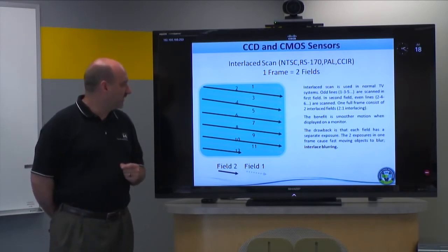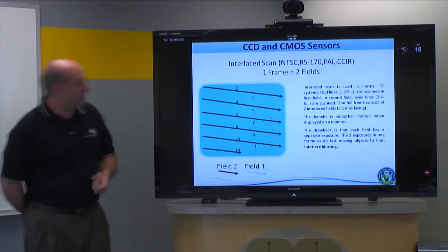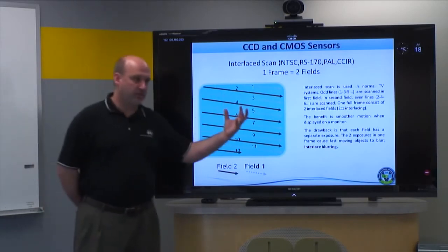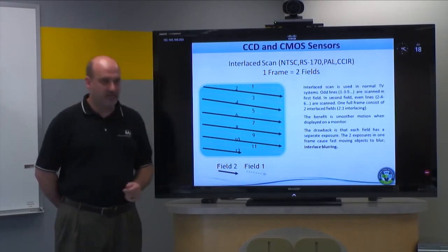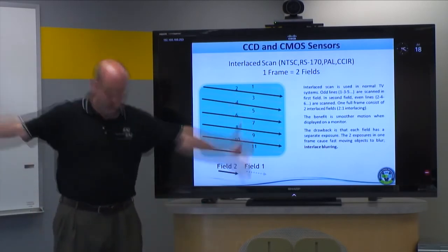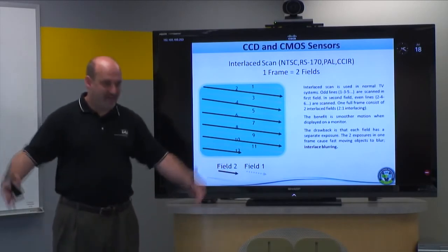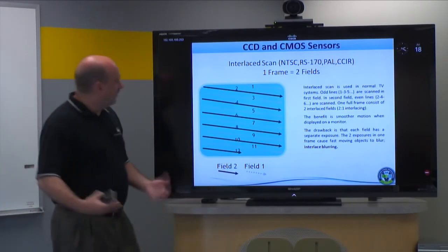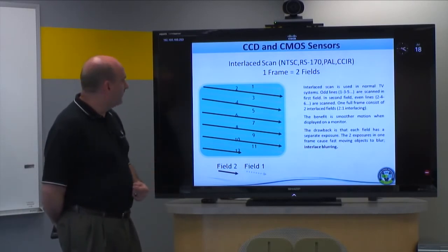So essentially, what the Americans came up with in the early days of TV and the NTSC system was, we'll interlace these. Instead of having to get everything into a high bandwidth signal and read them out and then recreate it with high speed scanning on a CRT, when your TV in 1940 was this big and full of large magnetic devices inside, they simply slowed the scanning rate in half and read out half the number of pixels.